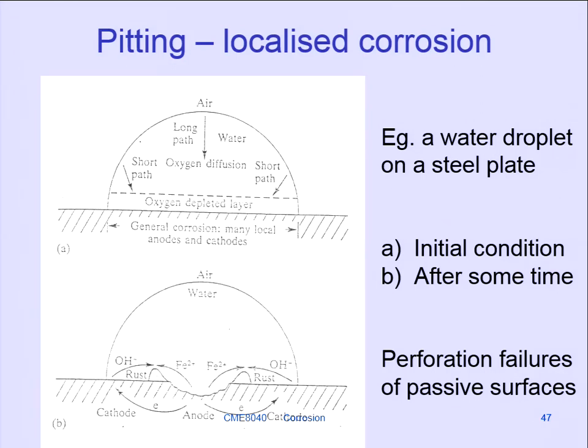And that means that's 4 electrons. Okay, so that's your cathode process using up oxygen. So the oxygen has to diffuse from the air into the solution and then be used up at the cathode. So it's a diffusion limited process. And what eventually happens within the bubble is you begin to run out of oxygen in the center of the bubble.